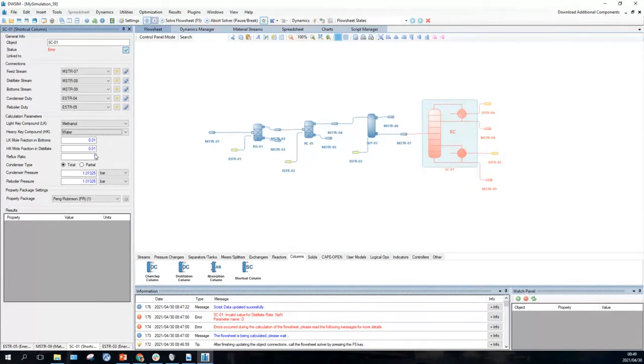All right, let's have a look. At least the mass balance would still be the same. It will be approximately the same, because you've got the same specs for the top and the bottom. If you use 1.5, it gives the same condenser temperatures. Excellent. Okay. All right. So yes, it is the same, whatever reflux ratio you choose.